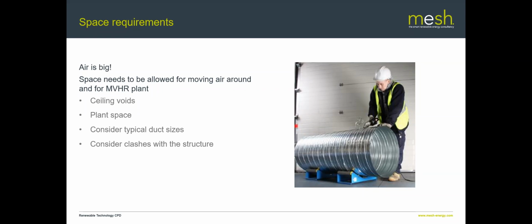And that's one of the places that quite often trips people up, is that they design in large ceiling voids, and then you have one steel that runs through the middle of that ceiling void, which obviously acts as a barrier, and unfortunately air can't pass through a steel particularly well. So we just have to be mindful of that all the way through the design process, considering any of those clashes.